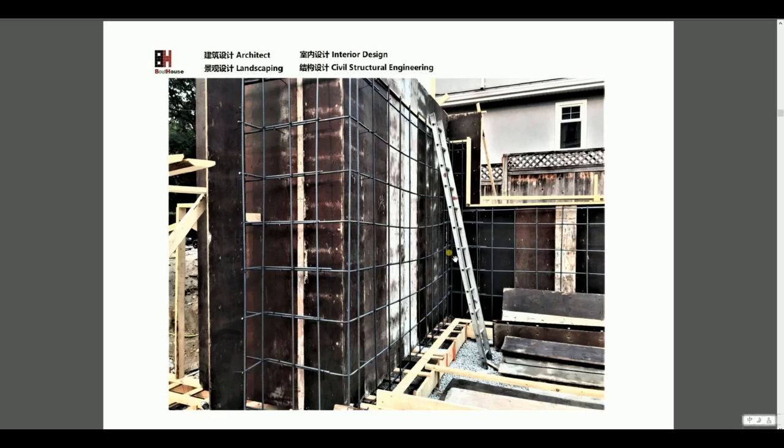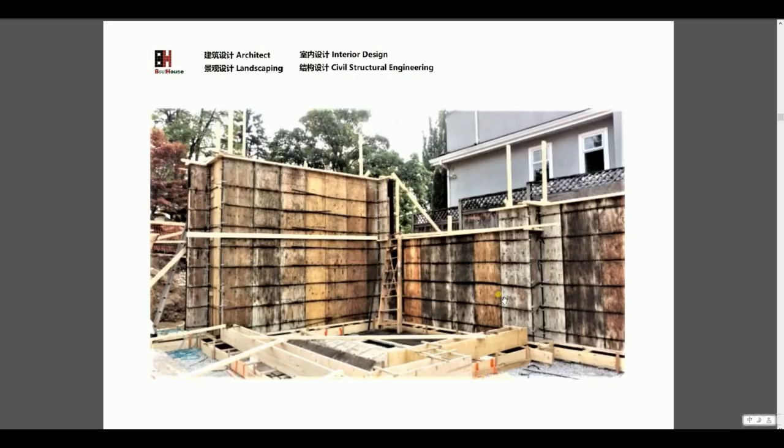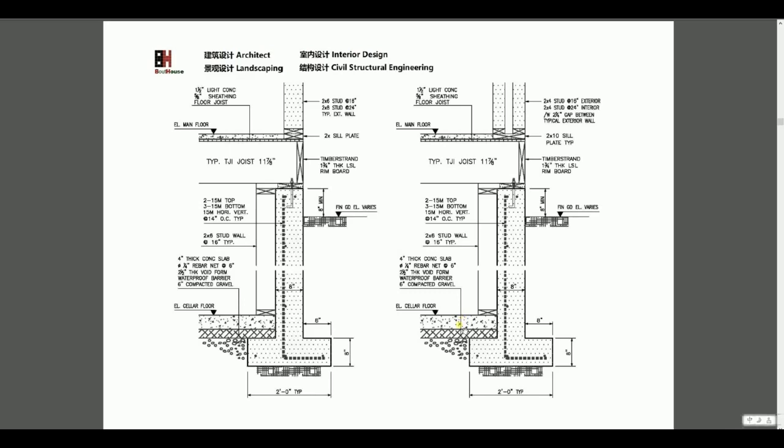When the reinforcement is complete and the form is complete, they have the inspection from the city. If approved, they will pour the concrete. Yeah, this is a form. The form is complete, so after inspection we'll put the concrete here.